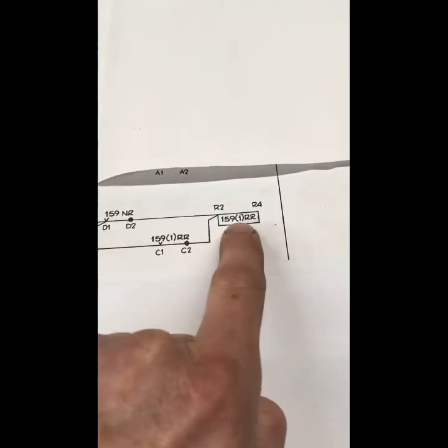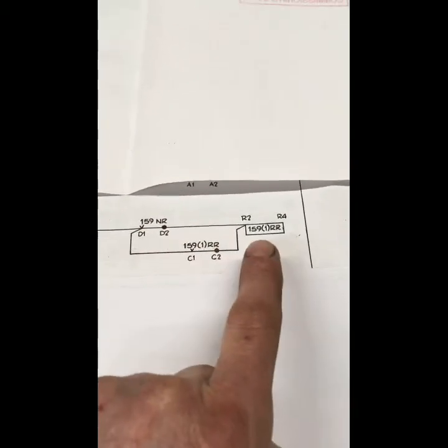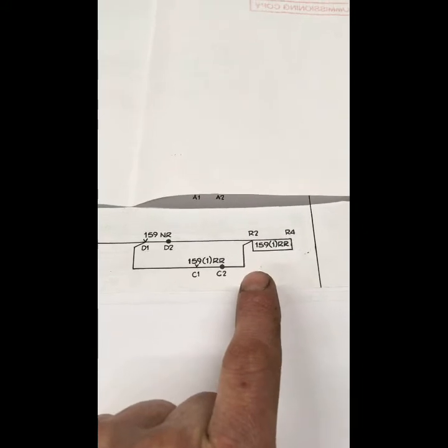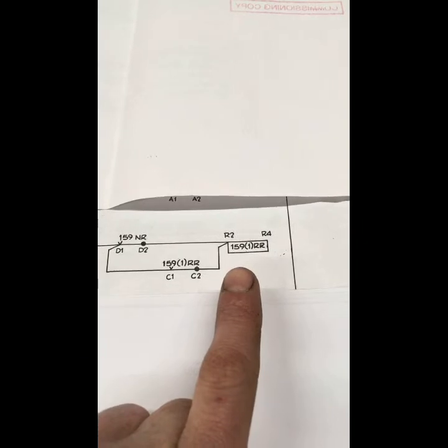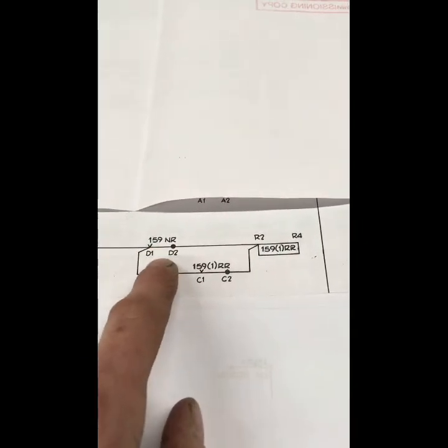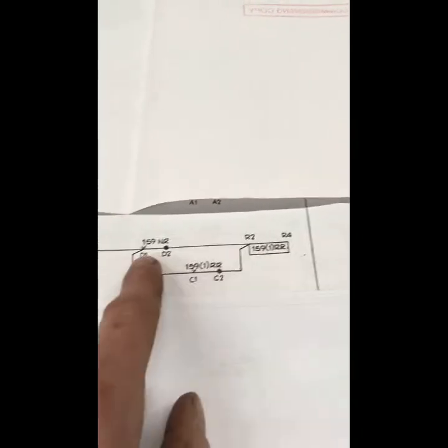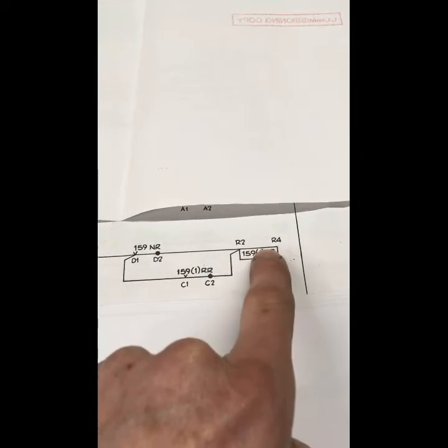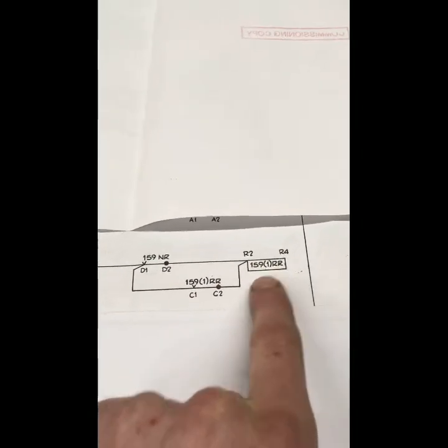This will then operate, by which time this will then drop out quickly. This can be a problem if you're in relay rooms that have a lot of feeds off a single bus bar, and the voltage drops off so quickly that before the RR can pick, the NR's dropped. So this momentarily holds itself up while this operates, then this quickly drops out. Once that has dropped out, because this is already picked, it's already held up through its own back contact. This is the front contact of this relay. So it's a pick and stick circuit.